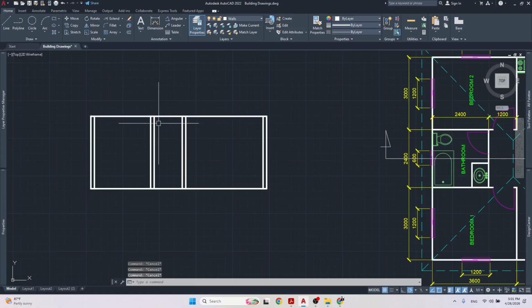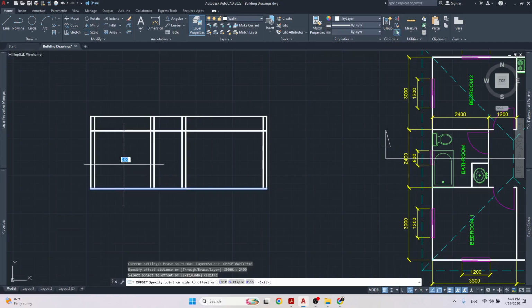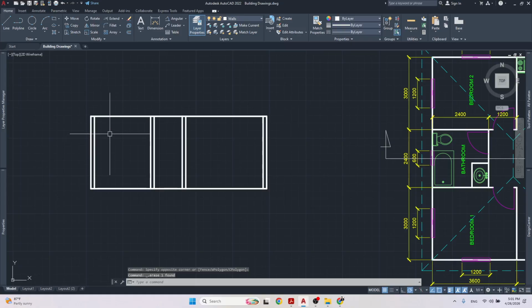All right. If there's a ceiling, it might tell you the ceiling is, let's say, 8 feet from the top of the floor. So you might have to offset a line 8 feet, 2,400 millimeters from the floor. That's the ceiling, and above here is where the top of your wall plate is and all that. But let's assume there's no ceiling.